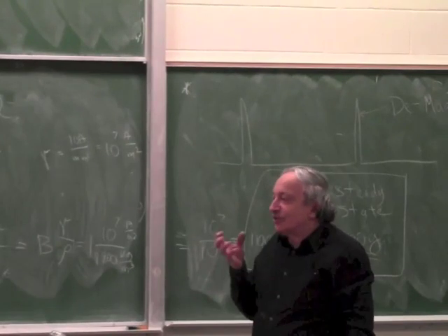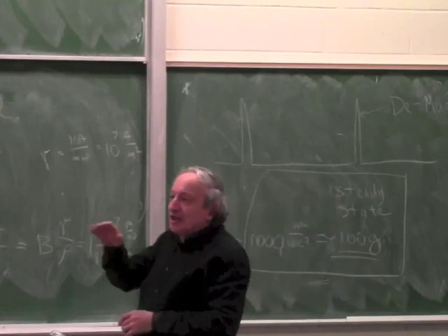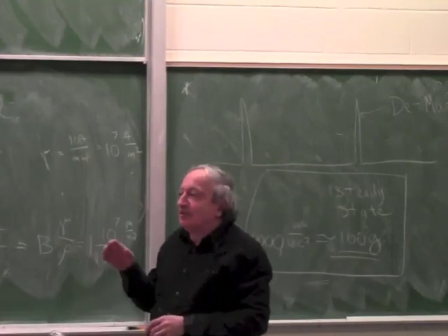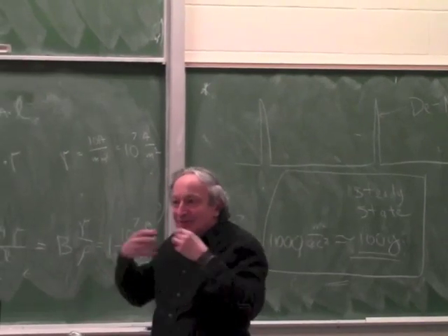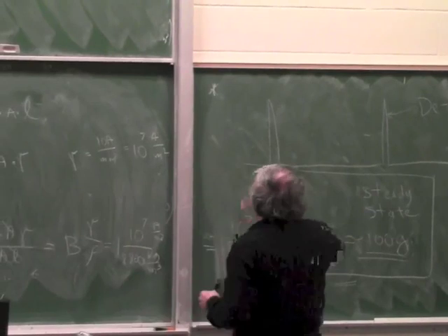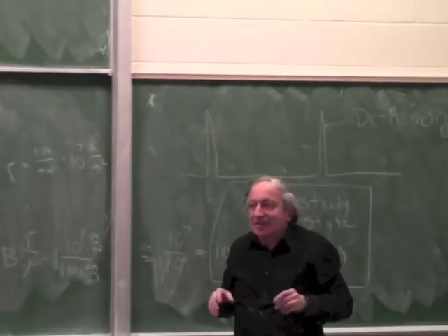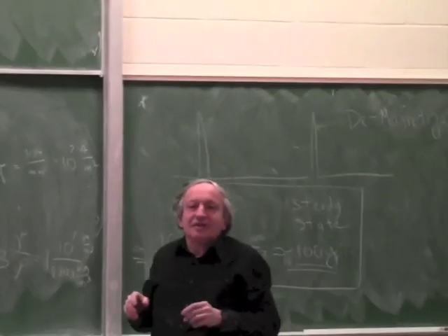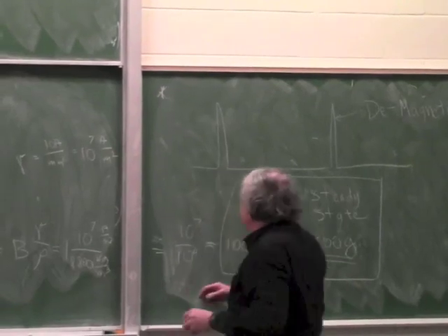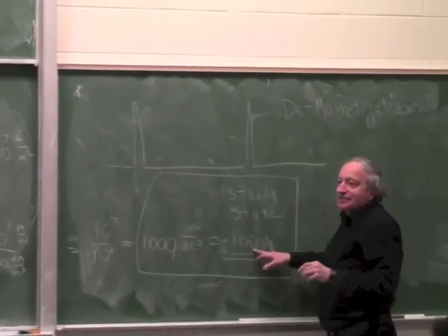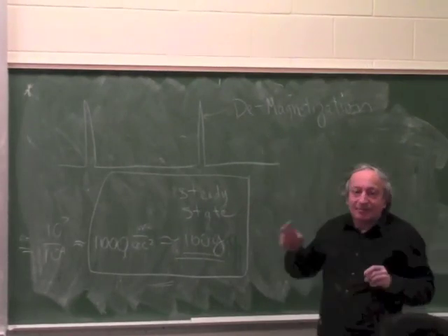Loudspeakers have a fairly strong and fairly big magnet because their average current is low, but from time to time you get some pulse in the music. When somebody hits the drums, the loudspeaker has to jump. You need a very big current, so you want to make sure it doesn't demagnetize it. So for moving coil actuators, which have to work beyond that number for a pulse, you have to make sure you don't demagnetize. Basically that means a big magnet.